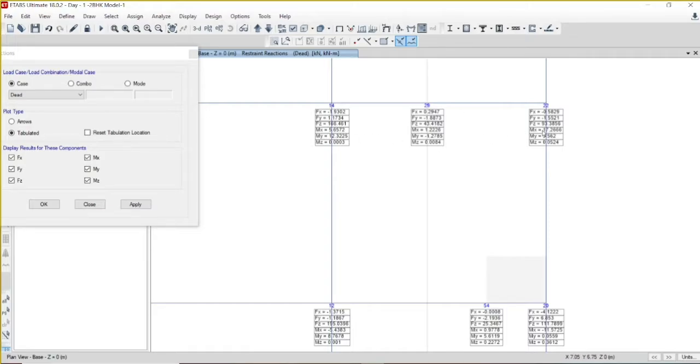But here in X direction, you are having 17.226. So these are the notable moments. If you are looking into live load only, let us apply this, and we can see that due to live load, the reaction is very much less. Around 192 kilonewton of load was here, but due to live load only 43.6 kilonewton. You can have a look in each and every reaction.